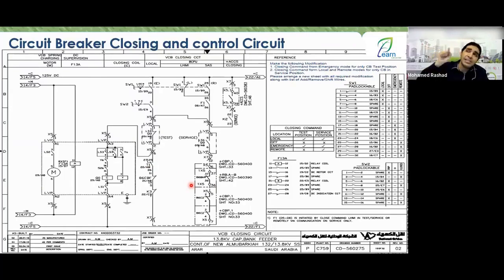So there must be something here to prevent you. You must reset it. Or the person sitting at the SCADA might press close, thinking the fault is gone, and he presses close. No, even if he presses close and the contact is closed, he will find this path open.